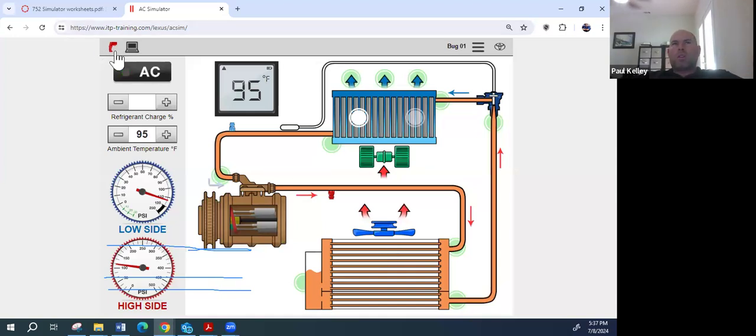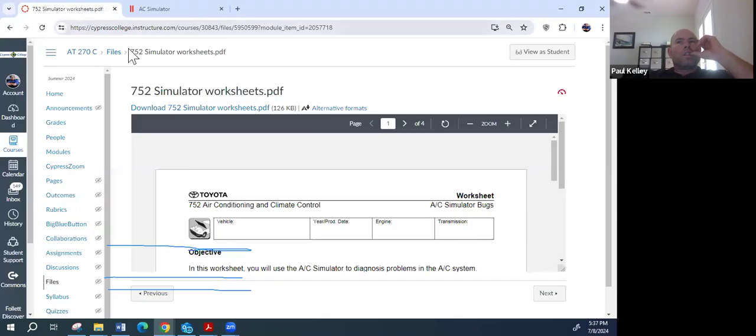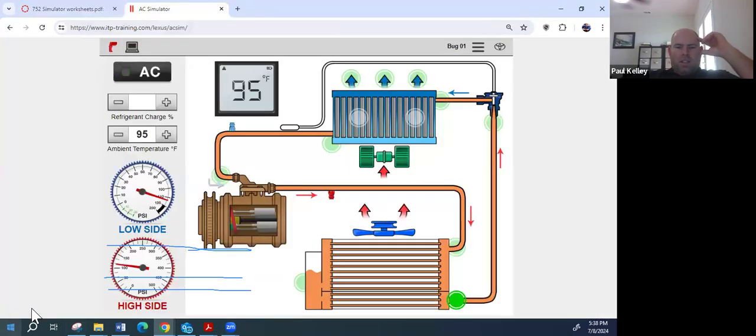and we could get the thermometer, and we could go ahead and hit these, and these would be super high, right? So if the temperature is hot, the pressure is high. That's physics. That's the relationship. Temperature is hot, pressure is going to be high. So we could check the temperature and the pressure, and you know what? They look fine, so we have no reason to think that condenser fan is an issue. So I would go ahead and say there was one left, wasn't there?